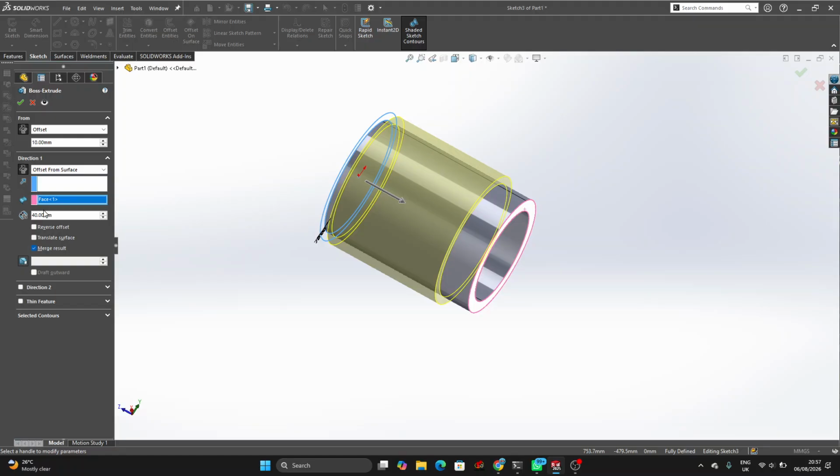That's what assembly means. But you can actually make a part, normally a part model that you are designing here, with more than one body. That's why they call it multi-body part. It works in part modeling, rather than making one single part have, like, 3 bodies. As I'm doing this extrusion now, it is automatically checking this merge result for me.